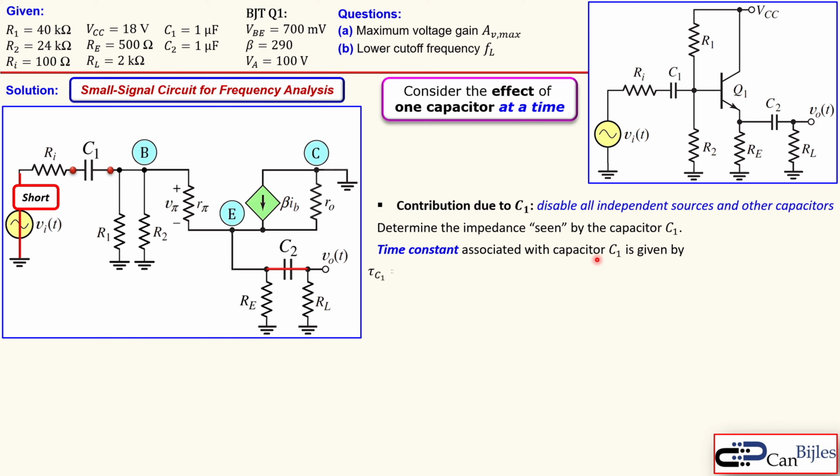So how do we do that? Well, we determine this capacitor and the impedance associated with that one with a product, which will then be a time constant. So this one, C1, is the thing we need to determine. That is the impedance. Okay, so we look first here into the Zi, so into this node that is again the same Zi as we have done it before, and that is what we first need to determine. And the series combination of this Zi and the Ri, that will be the impedance seen between these two nodes by this capacitor C1.